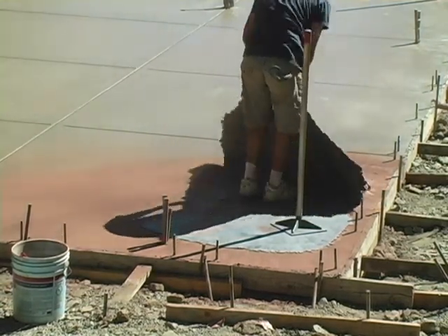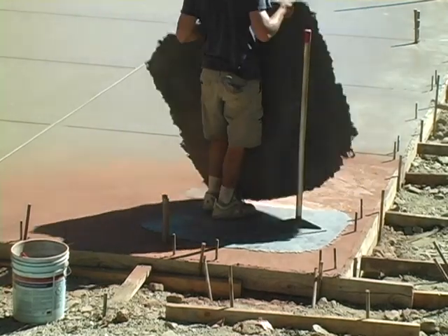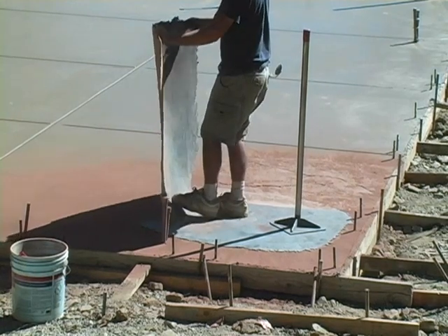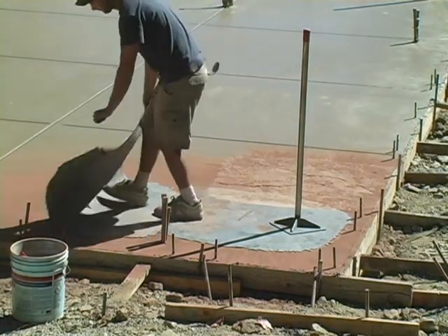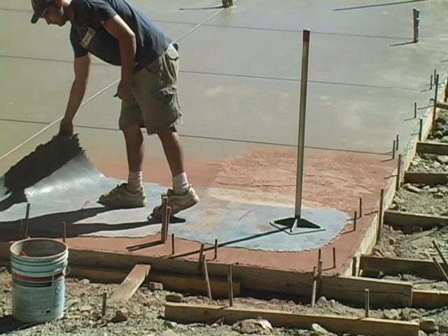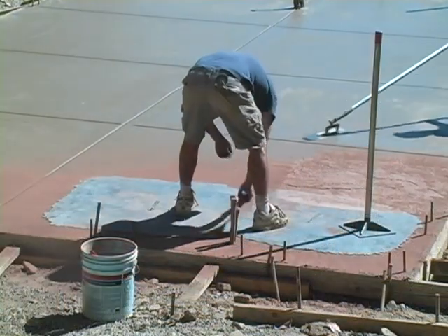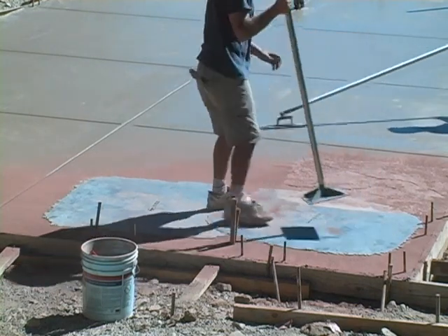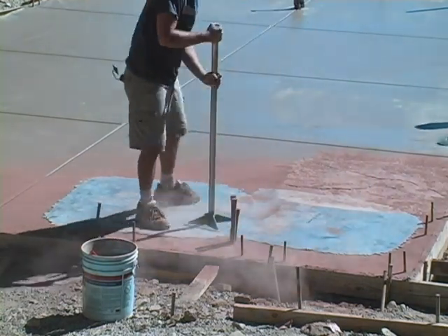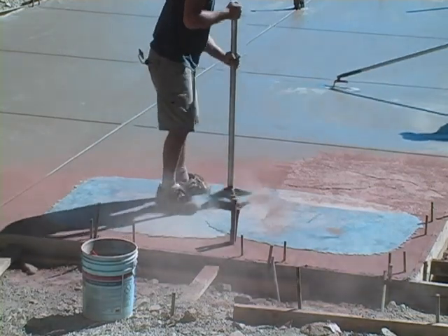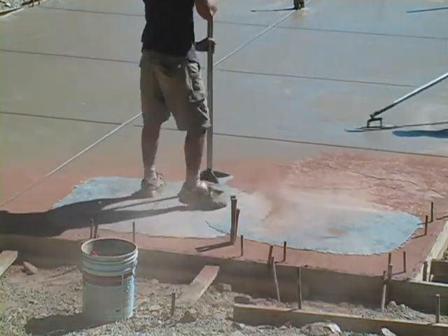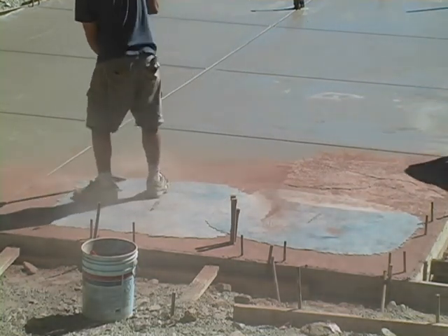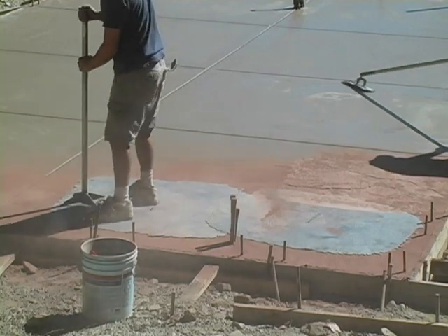And again, slowly peeling it back rather than trying to slide it out of position. You'll notice when we turn, it's going to be hard to tell here because we're turning directions, but when you add the next stamp pattern down, you always want to turn it 90 degrees from where it just was so that you don't pick it up and lay it down in a line, because then that pattern will start to repeat itself and you'll start to recognize it in the finished product. So by taking your second stamp and rotating it 90 degrees, you'll get a much better, less predictable finish.